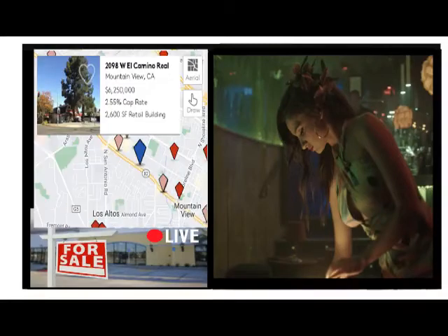Lead-based paint. The presence of lead in paint used in housing is a major health concern. Deteriorating paint releases lead. Renovations can release large amounts of lead into the home as well as the surrounding soil. The danger of lead exposure to adults includes high blood pressure, memory and concentration problems, and difficulty during pregnancy. The danger to children includes damage to the brain and nervous system, behavior and learning problems, slowed growth, and hearing loss. Encapsulation using special paints that prevent lead from leaching through to the surface may be the best preventative.